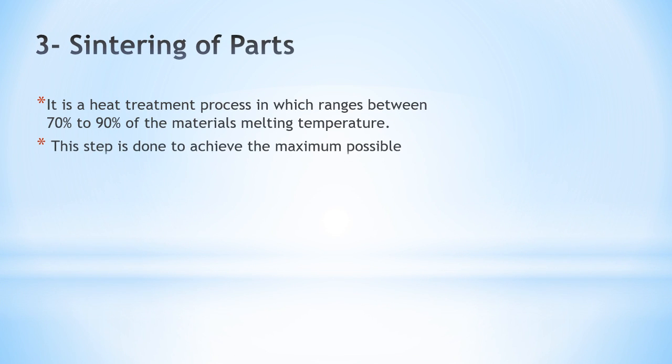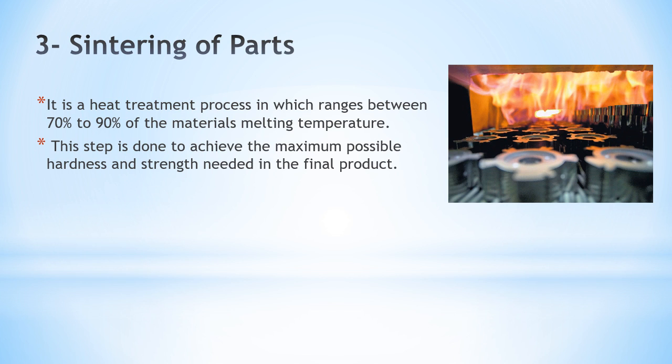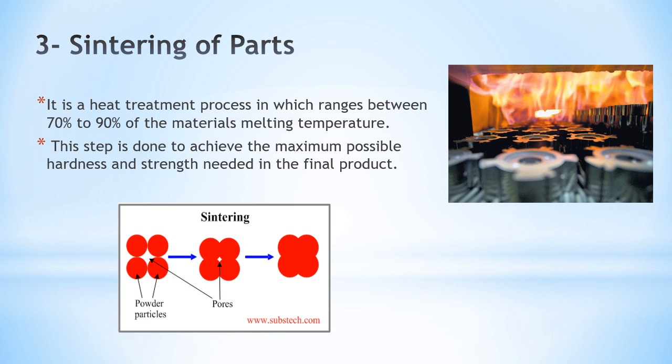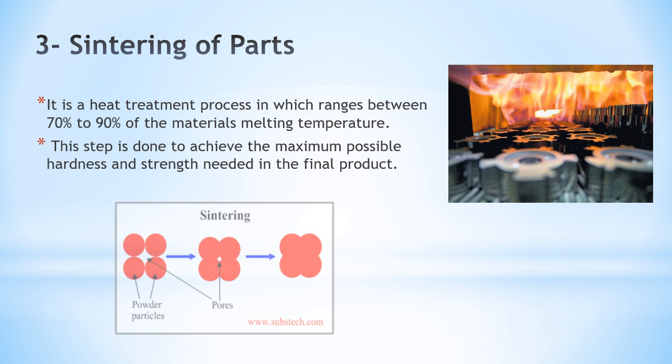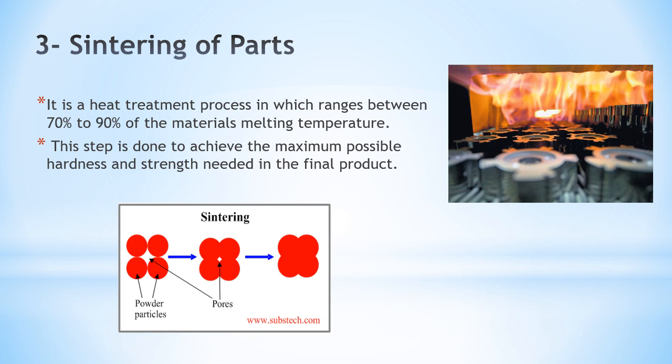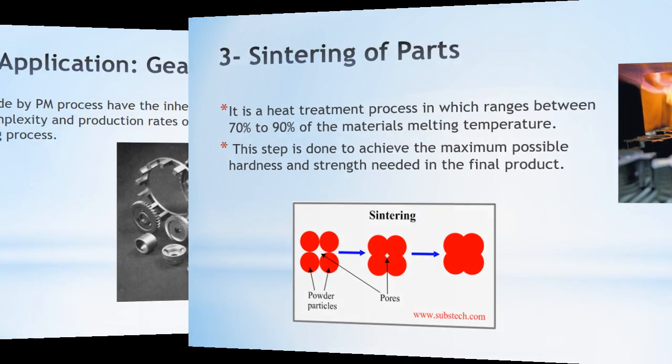Finally, the sintering process is done. It is a heat treatment process applied on the pressed powder. That is in order to melt the particles to fill the gap between pores. This step is important in order to achieve the maximum possible hardness and strength of the final product.